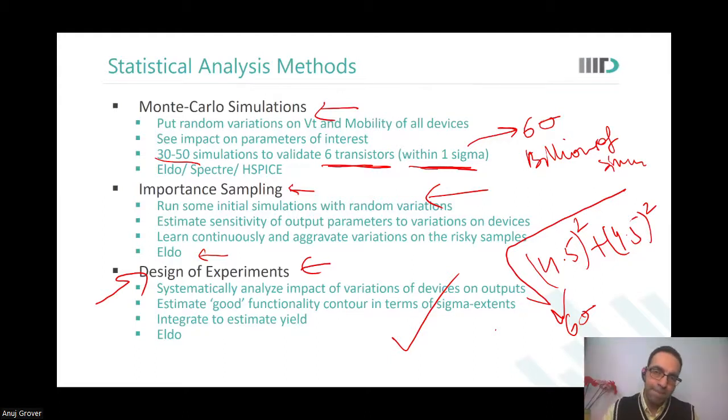So with this example of design of experiments, you took 4.5 sigma considering the write margin operation. When I qualify a bit cell, I will have to qualify for all the failure metrics, right? Yes. So you will run a different design of experiments for SNM, a different design of experiments for read current. You'll have to do those separately.